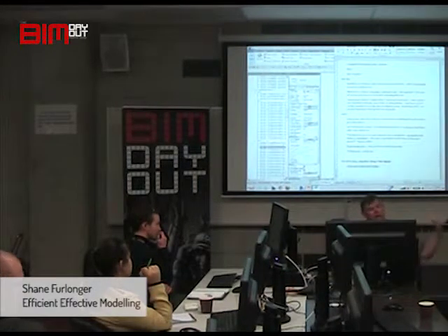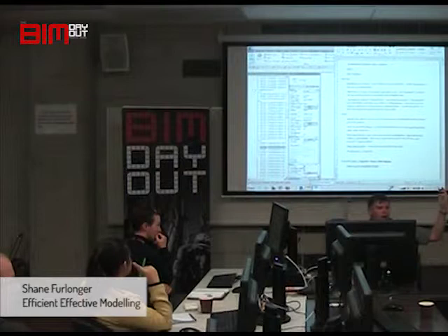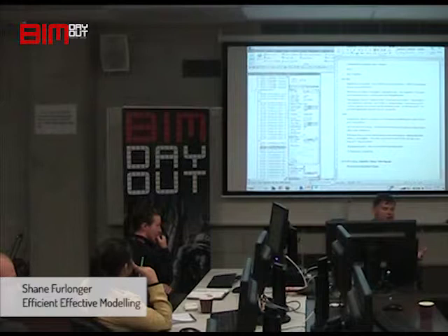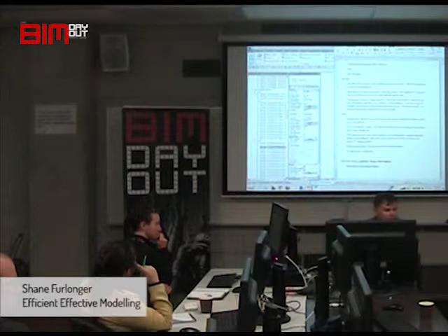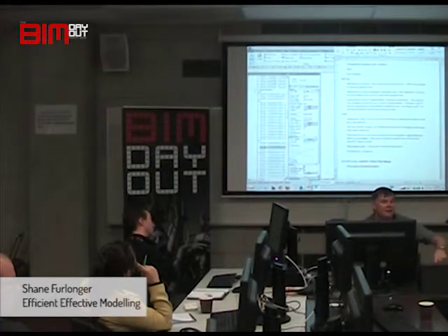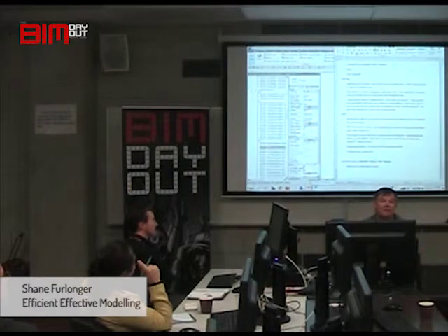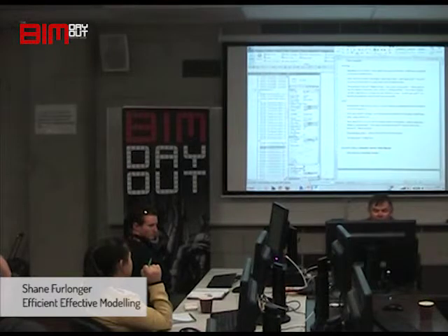So balconies are a good place to have unconnected because you know you always want it to be whatever it is. I always make it more than what the law is anyway, because you always get stupid things with tiles and God knows what else build-ups, and the last thing you want is the builder coming to you and saying, you said it was 1,000 off there and now it's only 950 and I've got to rip out all the balconies. So just a word of advice, put them up to at least 1,100. That way you never get caught out. Well, it's very unlikely unless they make a big cock up on site.